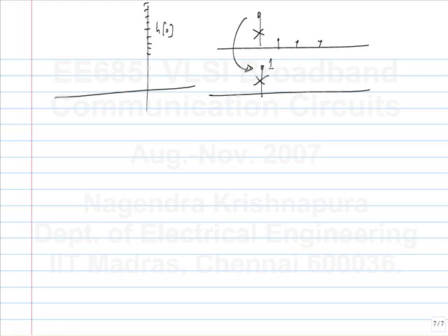It is the same thing. You can think of adjusting all the taps of the filter, but especially for circuit design, it's more beneficial to think of it as you have some gain of the filter, and that gain you have to increase if the ISI is large, because the main cursor tap keeps on reducing. Once you fix the main tap or the gain of the filter, then you can adjust the rest of the stuff to do equalization. So if you have 3 taps like this, you have only 2 degrees of freedom: the ratio of this to this and the ratio of this to this. That's what you want to adjust for equalization.